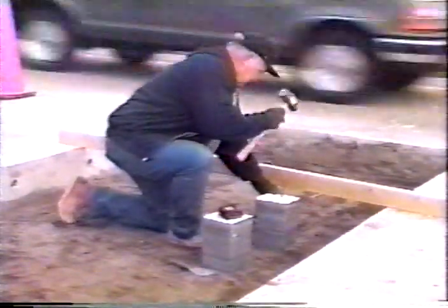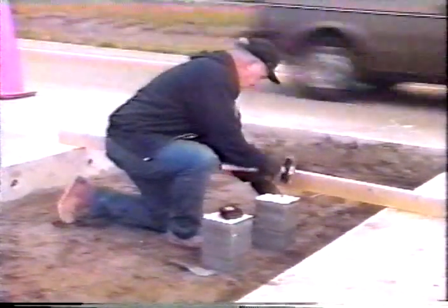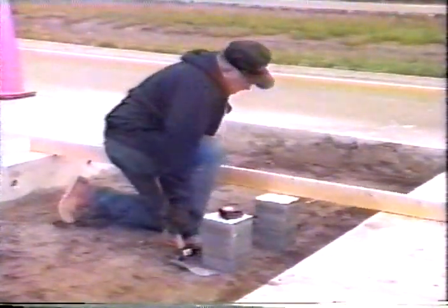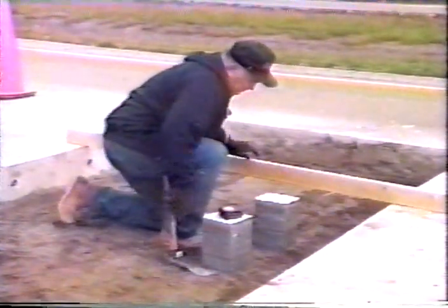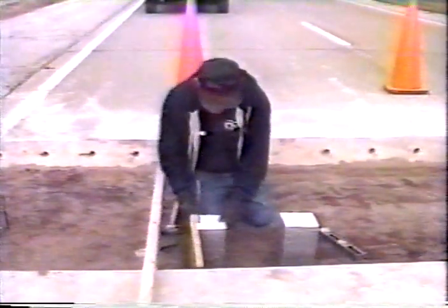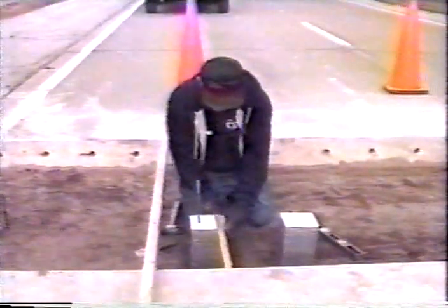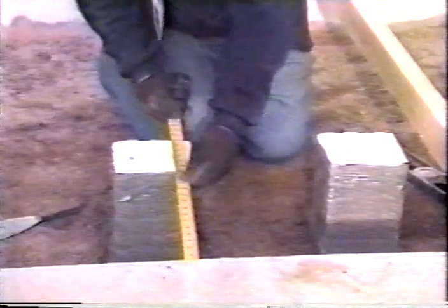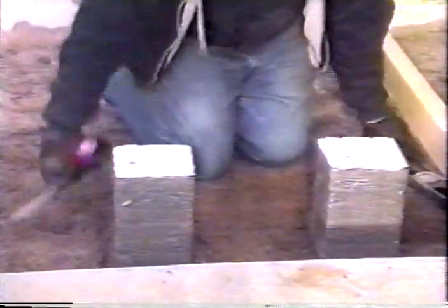To determine pulse velocity for full-depth construction and patches, foam blocks are staked to the subbase before concrete placement. They will produce blockouts in which the pulse velocity measurements will be taken. The blocks are spaced at the same nominal distance as the specimen transit distance, since velocity at early ages can be influenced by travel path. For example, if the pulse velocity was measured on 21-inch long beam specimens and correlated to beam flexural strength, the blocks should be positioned 21 inches apart as well. Concrete is then placed around the blocks.